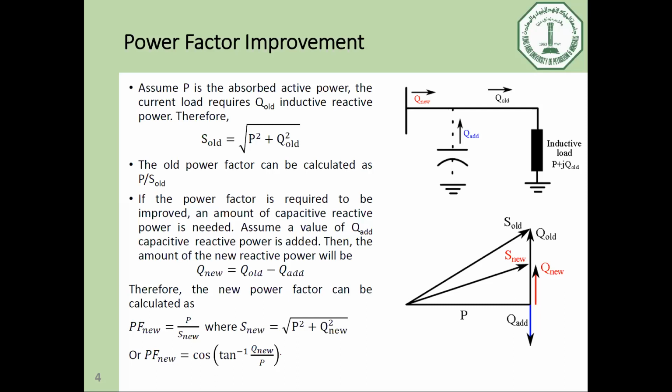In our grid, what is the majority load side? Is it capacitive or inductive? Capacitive in the grid? No, on the contrary. The majority of the grid is inductive, because where can you find capacitor loads? What are the capacitive loads in our life? You may find some capacitors in electronic devices, is it right? But even these capacitors in electronic devices are on the DC side, not on the AC side. However, the overall power consumed in the grid is inductive.